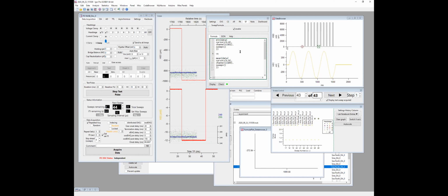I mean, you can do QC on your pre-pulse baseline, for example. And if you say, well, this doesn't look good, or it's too noisy, it has the wrong value, well, you can either adjust some setting, or you can run the test pulse some more and reacquire, or abort the current sweep and then start over. And this, of course, greatly speeds up data acquisition, because you don't want to run a 10-second stim set if you know after half a second that this will not be passing quality control in the end anyway. So you can abort early.